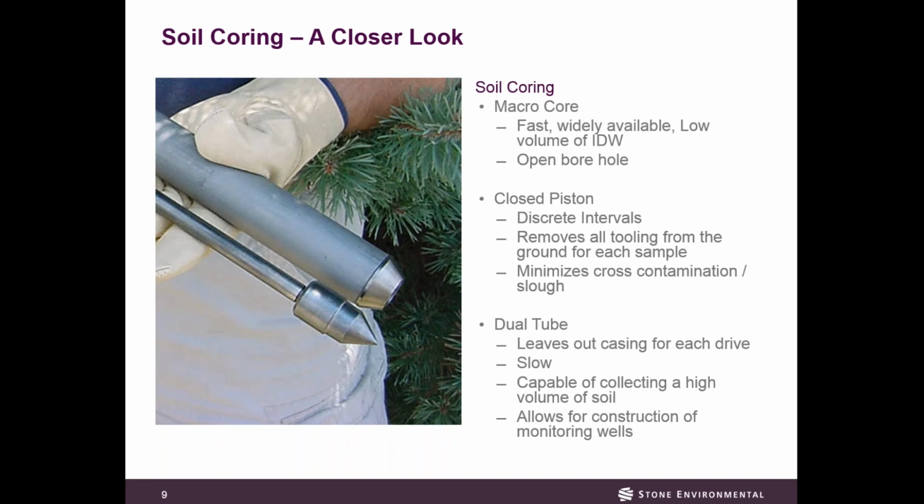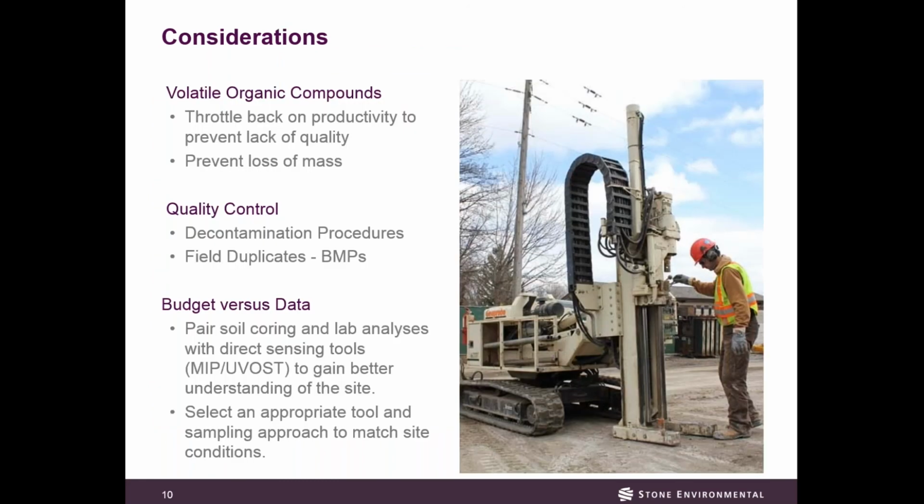So some considerations on the analytes. So for VOCs, I was going to set up a little experiment where I had a core and timed it. A core comes off the rig, your driller might rip open that acetate for you, and they lay it on the table, top's right, and you're set to log it. In a lot of work plans, you have a PID and a box full of Ziploc bags, and you take your screening samples and let them equilibrate for a bit and screen them after a few minutes. And in the meantime, you're logging all the stratigraphy in that core.